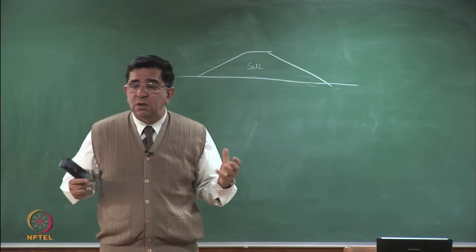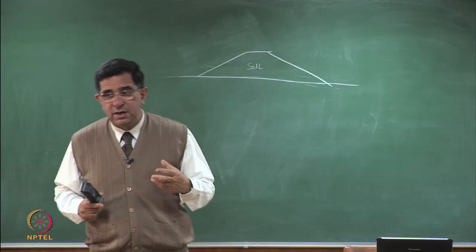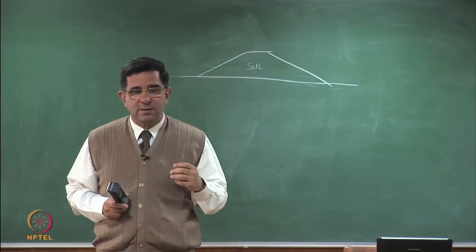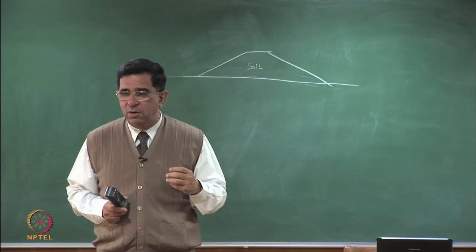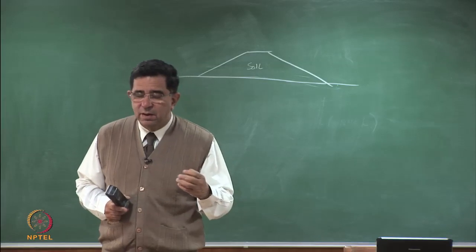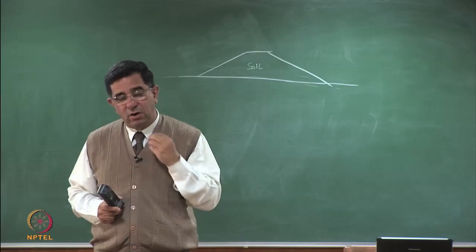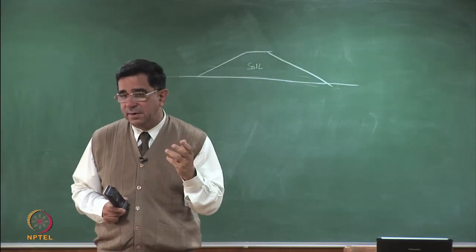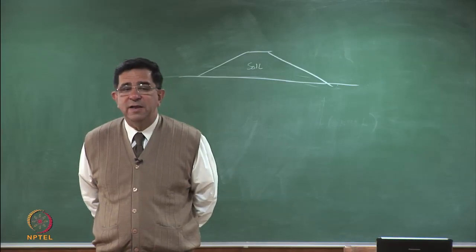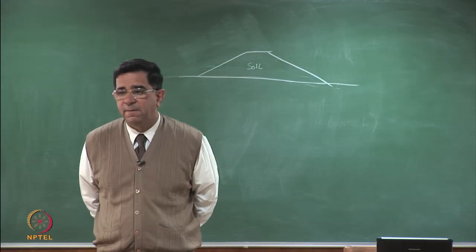What do you think of waste? Waste is definitely not a liquid, right? So it's going to behave more like soil. It's a three-phase media. So it will have solid particles, liquids and some air entrapped in it. So what kind of test would you do if I said that please get me the shear strength properties of this waste?